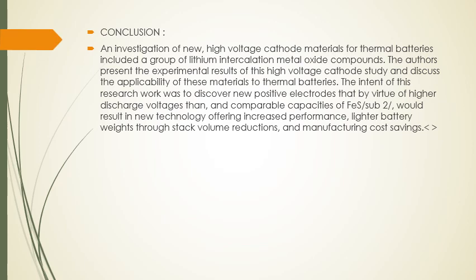Coming to the report and conclusion: an investigation of new high voltage cathode materials in thermal batteries includes a group of lithium intercalation metal oxide compounds. The author presents experimental results of high voltage cathode studies and discusses the applicability of these materials in thermal batteries.